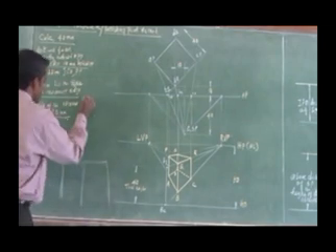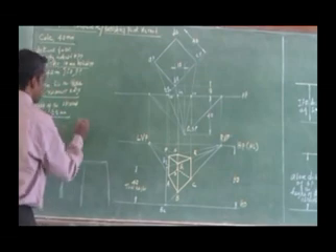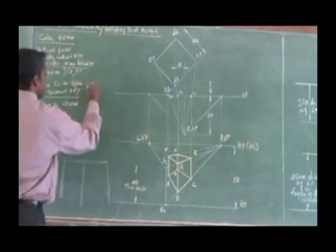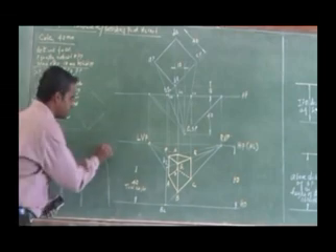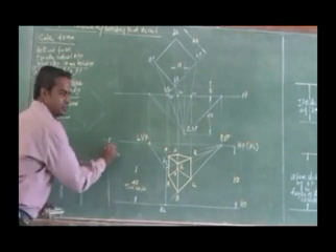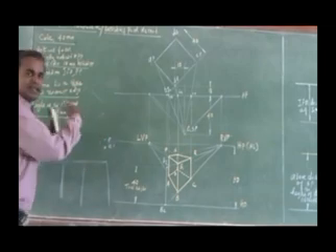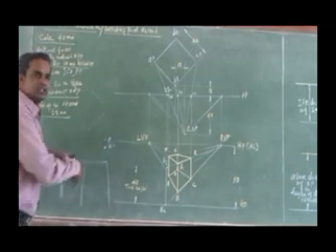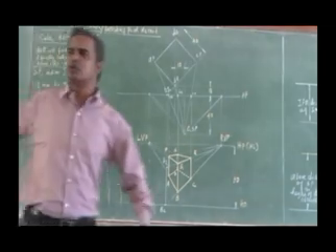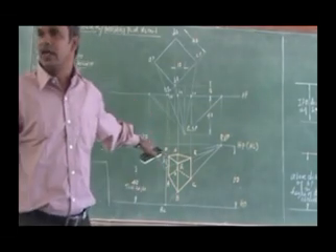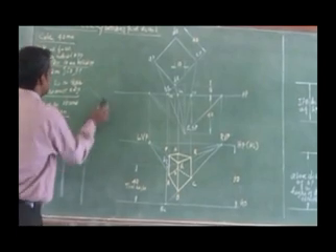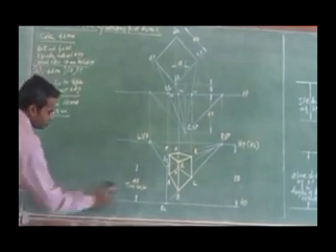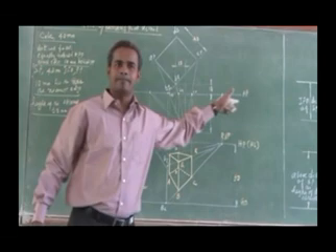And the top view will be like this, we have drawn already. Right. Previous visual ray line, you can mark station points E, E dash. And you can project, get the intercept, you can get the corresponding location of the perspective. Similar to the previous problem also, you can solve it. So this is two-point perspective, will give you a more realistic perspective view, since the faces are inclined.